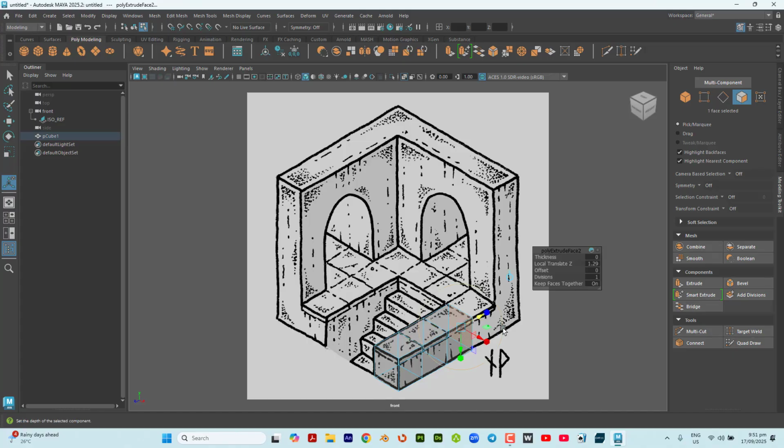Following the block subdivisions there, and then I can press Q, Control E, so I can just alternate until I am able to follow the whole reference, and then Q, Control E, drag there, and then I can just press Q, Control E. I can still do one more surface, let's say until there. Now that I'm done, I can press Q.